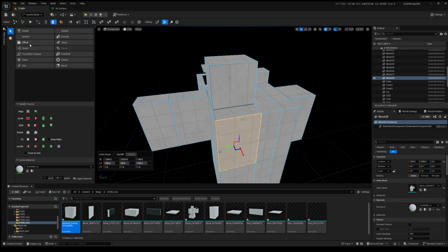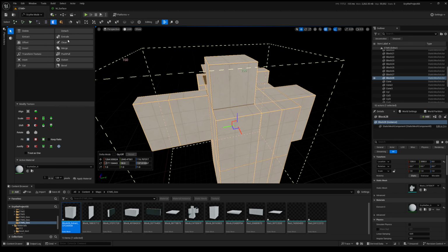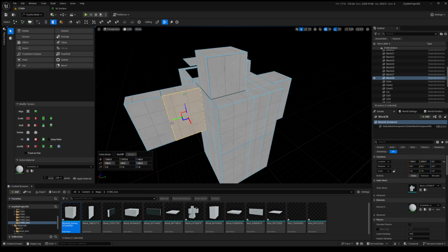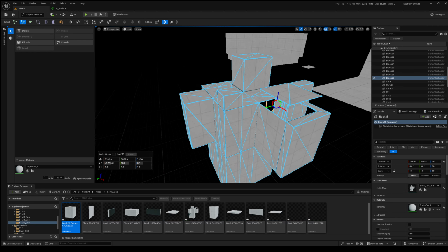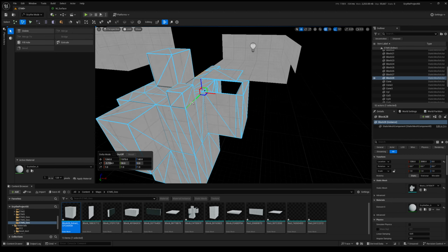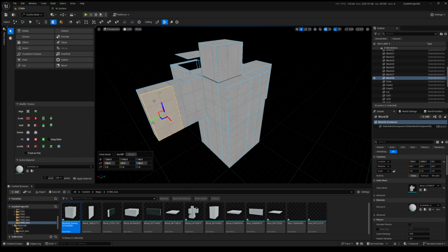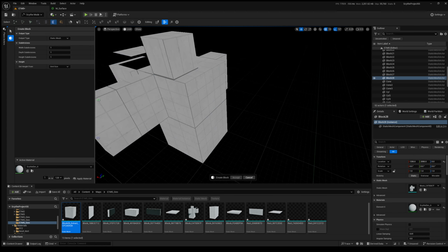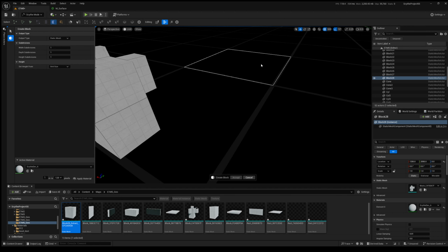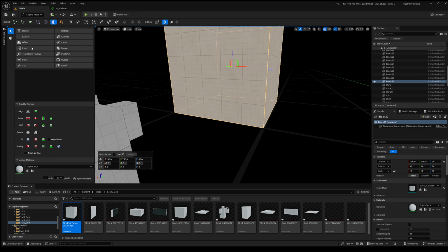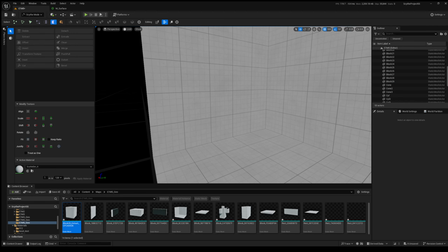Unlit here. Yeah, and also it retriangulates the mesh. So if you've made just a lot of sins with your mesh, then you clean it and it'll retriangulate, and you can see your triangles by clicking this here and seeing what the mesh actually looks like. We got invert. This flips the faces, so it's really useful, you could make a very quick room. I select all the faces here, and then I invert them, and we just made a room.